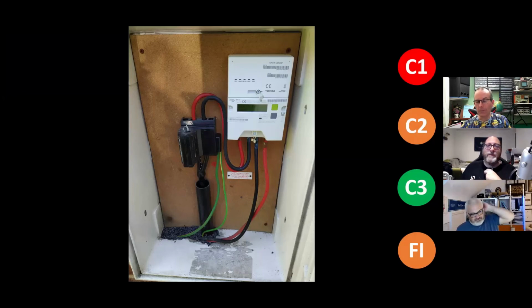That is a smart meter, and it's notable how big some of these smart meters actually are. They're actually bigger than the old mechanical ones that they've now replaced, which is partly why they've done this thing where you're supposed to put it in a specific place. So we've got 16mm tails there, and they go down in there, and they go inside the cavity wall, and then the consumer unit is on the other side of the wall as built. It's actually quite a common arrangement.